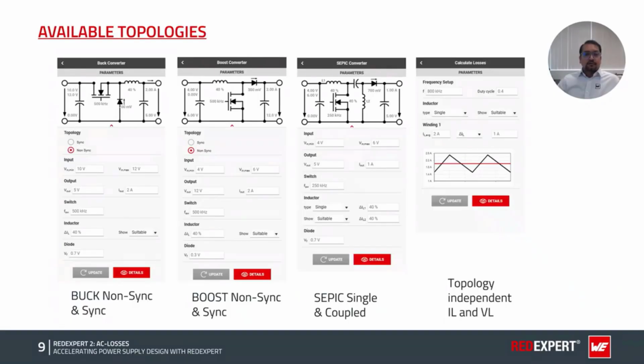REDEXPERT supports a wide range of converter topologies, not just the common ones. It supports buck and boost in both synchronous and non-synchronous mode, SEPIC for both single and coupled inductor variants, and a topology independent mode where you input the inductor current and the voltage directly. And this last option is especially powerful for engineers who are working with custom topologies that don't fit into the standard converter topologies.